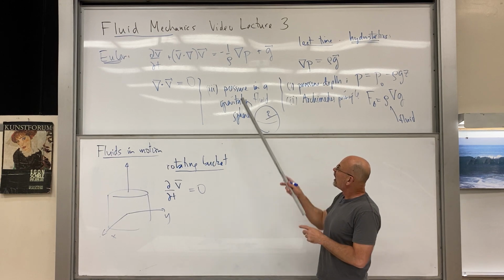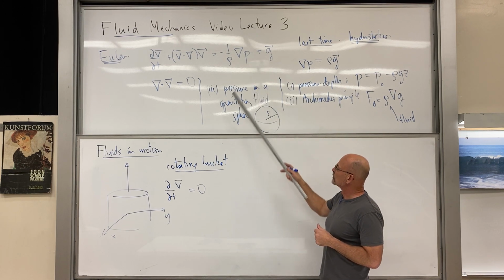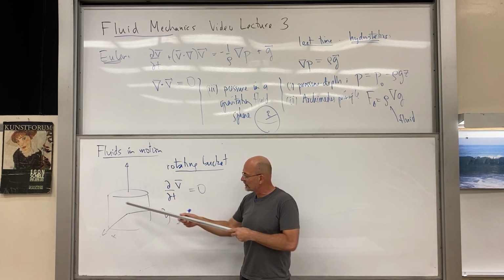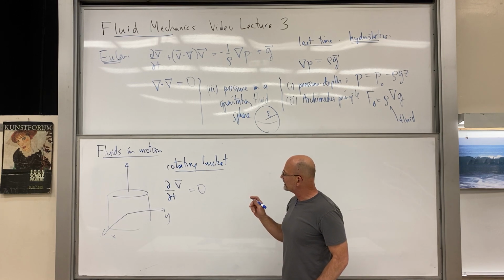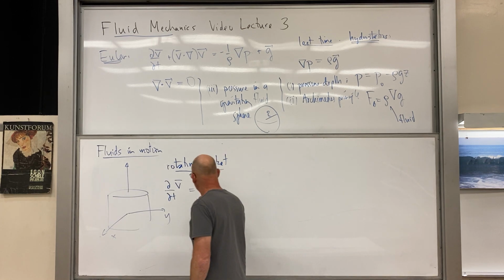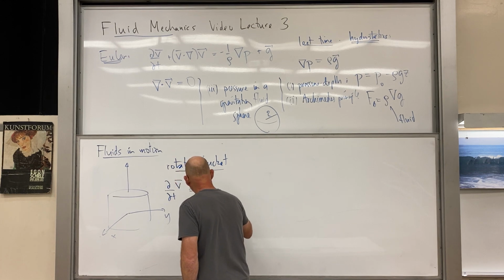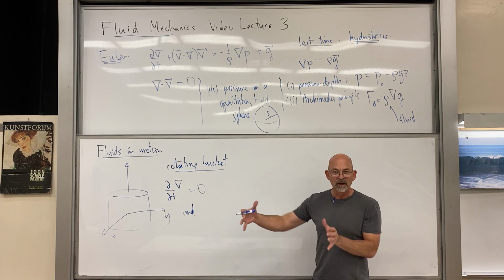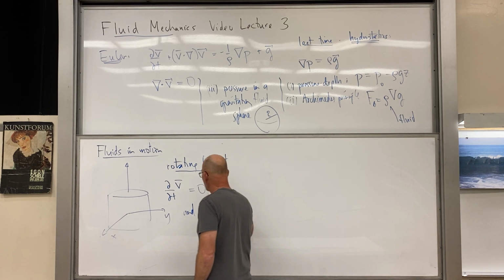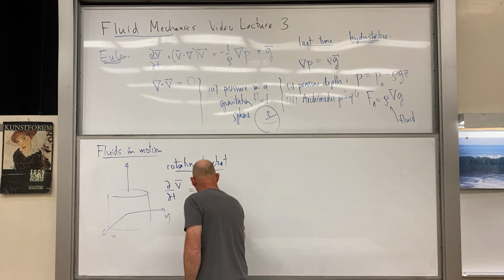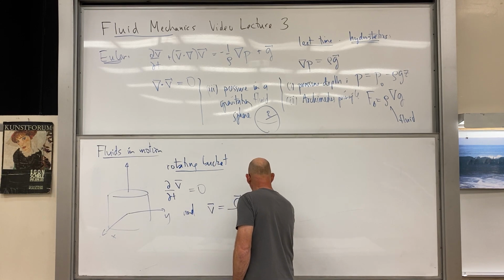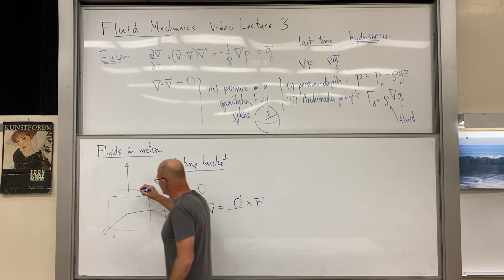So that is actually not possible with this equation, because we would lack that proper frictional component that actually exists, and that's what helps spin the thing up. Nonetheless, we're going to have the following. Since it's going to end up rotating as a solid, as a unit, we'll take that as the following. So the velocity field is just going to be omega cross r, and so we've got an omega vector